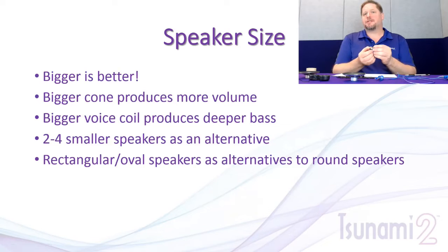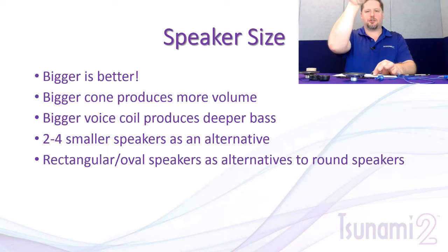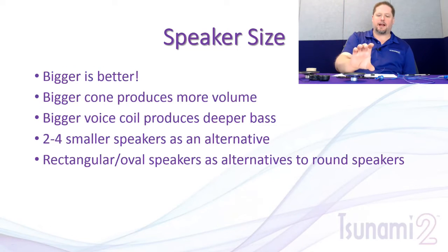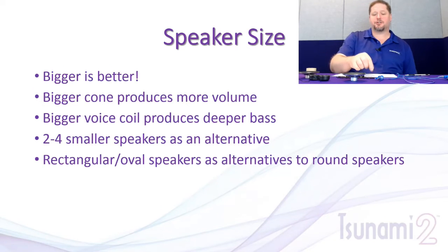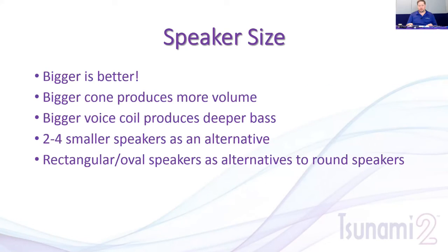These are able to reproduce down to 100 hertz frequency, but because they're so small, it's such a low pressure. When we were doing some testing with these not too long ago, we took a spectrum analyzer, and about 18 inches or so away from the speaker, you couldn't hear anything or see anything on the graph lower than 250 hertz. But when you put it right up on it, you were able to see that it actually is reproducing it, but again, lower frequencies are lower pressure, and so they didn't come through very strongly. So 2 of these is going to do a much better service for you, and we'll get into multiple speakers here in just a second.